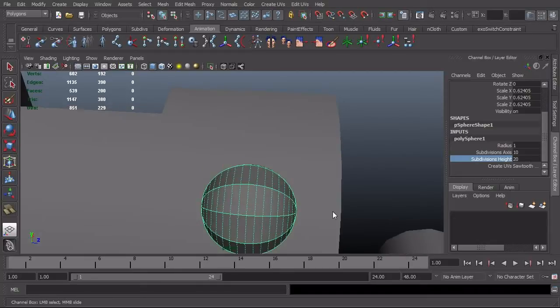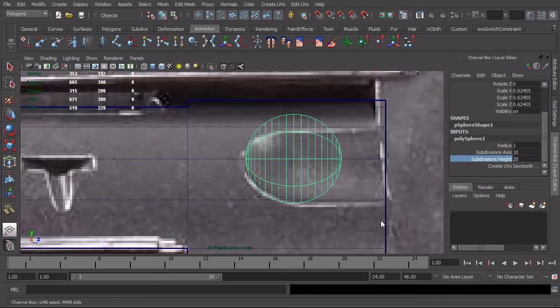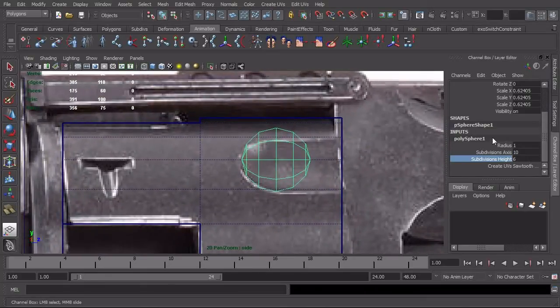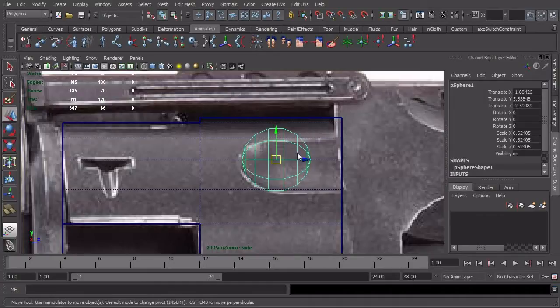And then as far as height goes, what you need to consider here is, as I drive this down, if I were to go down to 6 here, if I were to pull these spans back, see that angle that goes from the center line to the next line? That would be in our actual mesh. So I want to pick a resolution that has no center line, and that way I can just grab all the verts on this end and pull them out, and everything will match, so it'll be a nice flat line across that way.